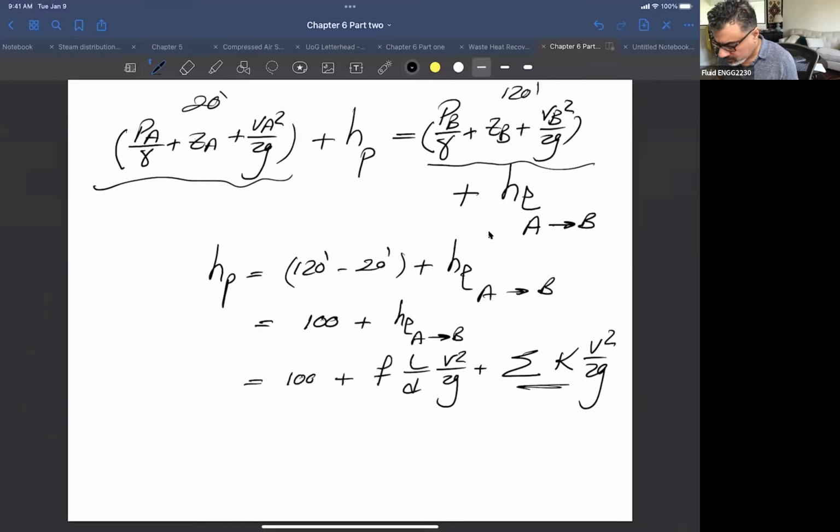Okay. So what we need to do in this case is start the same way as we did in the previous lectures. We get the velocity, we get the Reynolds number, we get the friction factor, and do all these kinds of things. So we have Q, which is area times velocity, and the pipe has a 2-inch diameter. So this Q here is 0.2 feet cubed per second. Let me put the area in feet squared.